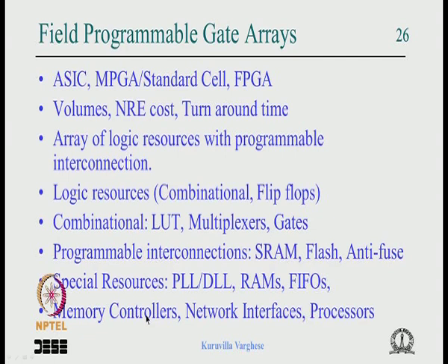It needs a lot of memory, and the DRAMs are used. DDR3 can be interfaced, and in that case a DDR3 controller implemented in FPGA resource may be slow. So there are hard kind of controllers in the fabric. Network interfaces, like the physical interface or the data link of the Ethernet and so on, okay, or at least the blocks used in the prominent network interfaces. Sometimes the complex FPGAs have processors built in, hardcore processors built in, so that you can implement a complete SoC solution within an FPGA, okay.